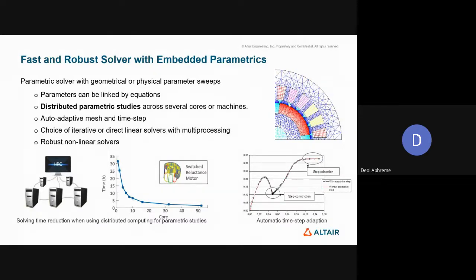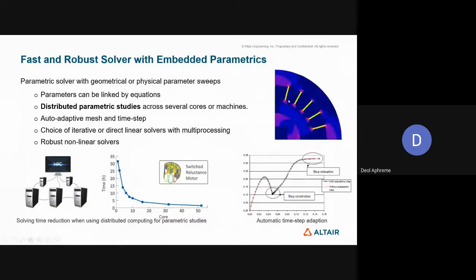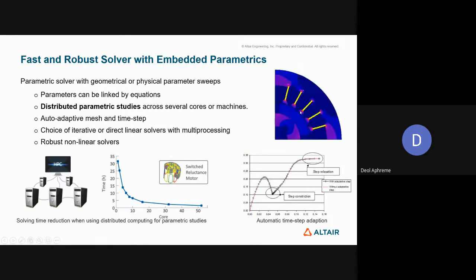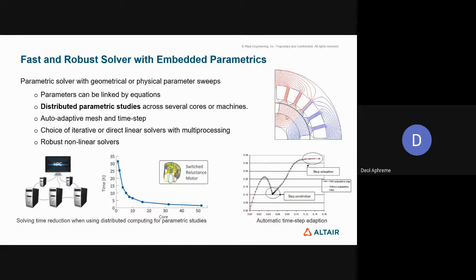As you can see in this image or this GIF, the width of the stator tooth is being simulated for different sizes, and the effect on the torque is again visualized. This might seem like a very long problem, in the sense that it took a lot of time to solve it. This is an SPM motor, a surface permanent magnet motor.